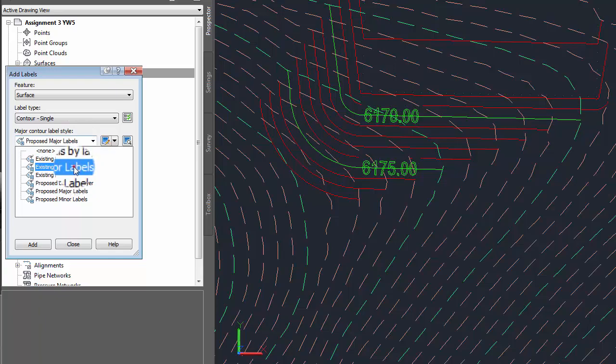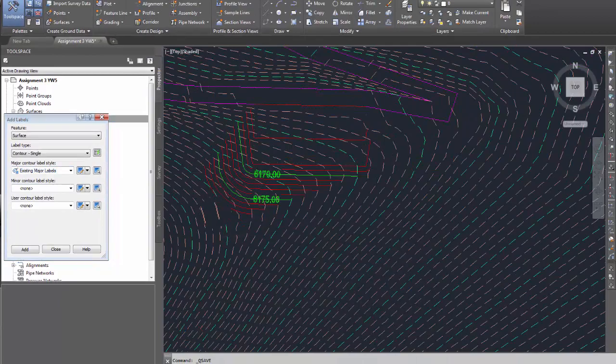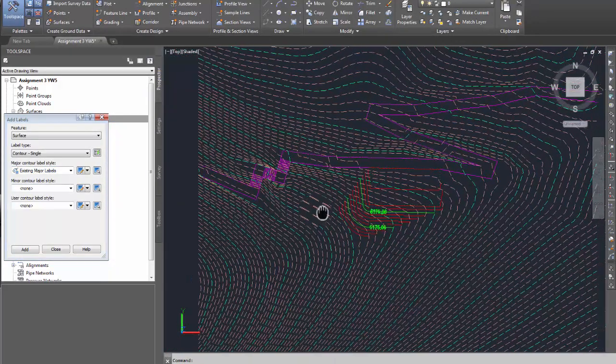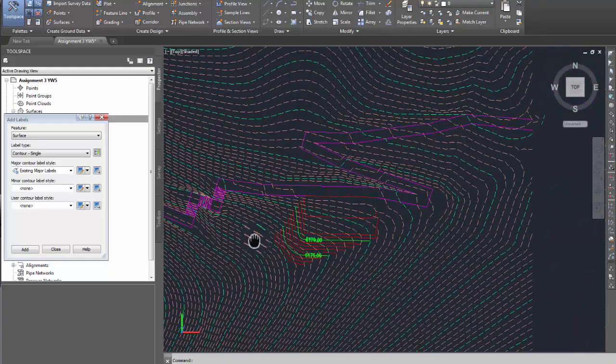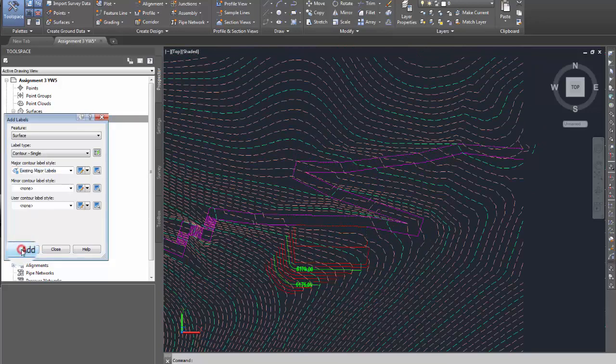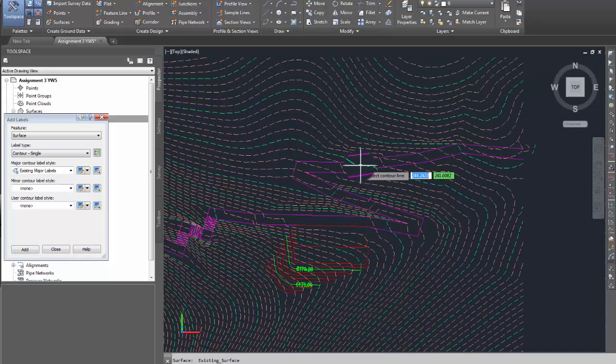major contours for existing. It's a bit more challenging, you have to zoom out. Again, labeling contours is stylistic. You want to keep them as far to the perimeter as possible and away from any of the new or meaningful information. So set your style, pick your contours. Keep it away from the important activity and align them as closely as possible.